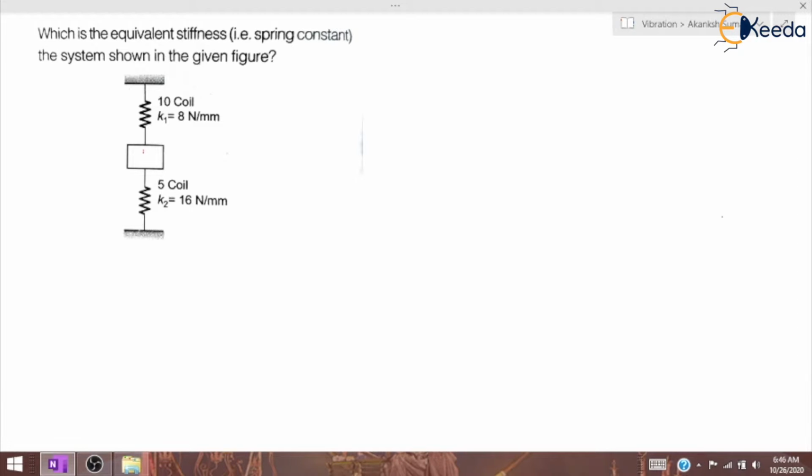the two springs. So first you need to determine the connection, whether it is series or parallel. I have told you the conditions. How can you find out the connection type, that means whether it is series or parallel? In case of parallel, there will be equal deflections in the springs. So you can see when the block moves in the upward direction, there will be equal deflections.